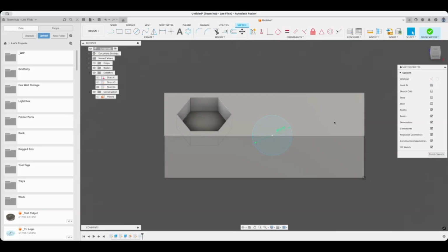All right. Let's just play with a conical curve. So if you hit create, go down and hit conical curve. Go like that, click once, click there, click there. And then we're going to do it again. If you'll let me, I'll go hit enter. And then let's do another conical curve.